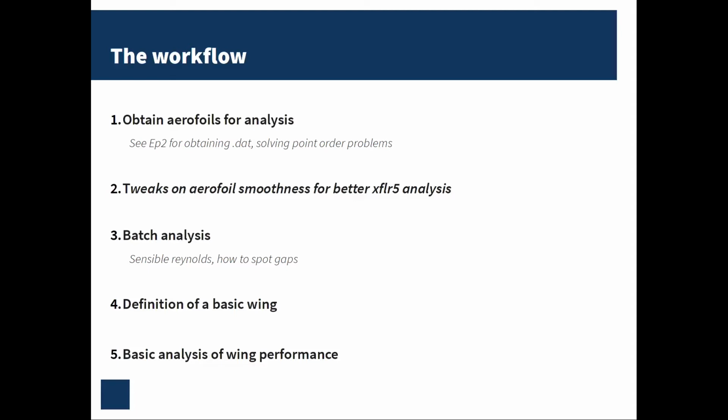The way it works with DAT files is you have individual panels, and if there's a discontinuity or two panels form too steep of an angle, the method, which for XFLR5 is XFOIL at its root, can lead to some interesting behavior. There are a few tools available in XFLR5 to sort that sort of stuff out, which I will go over at the import stage.